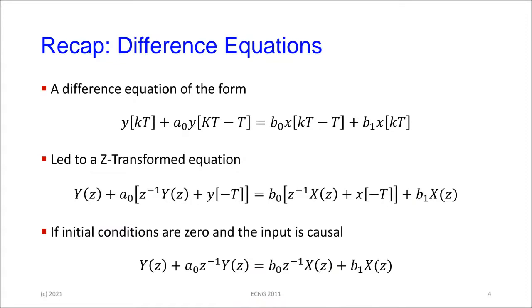And then we saw that specifically for discrete time systems, which is what we're dealing with now, the discrete time systems are represented by something called a difference equation. And the difference equation is an equation that represents the current output in terms of current inputs, past outputs, and past inputs as well. If the system is causal, then you don't have to worry about the past inputs, but the system itself may have memory that relates to the past output. And we know this again from simple digital electronics, things like shift registers, for instance, where it moves depends on where the current state is and where it was before. Counters do the same thing.